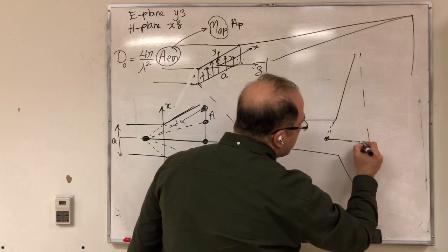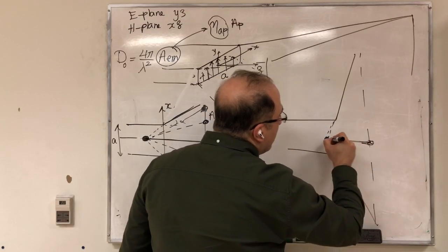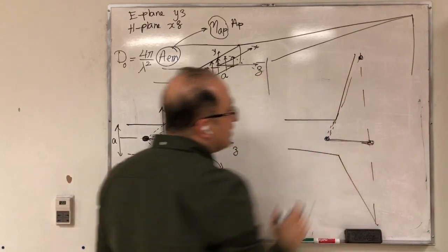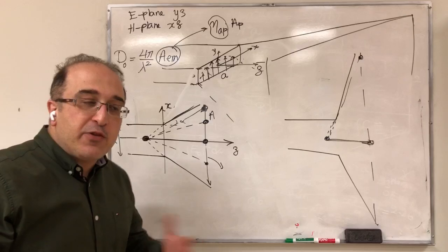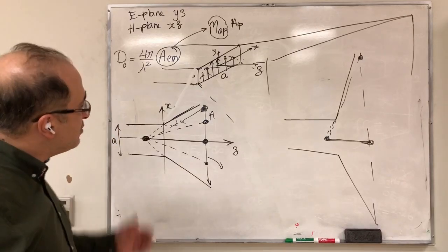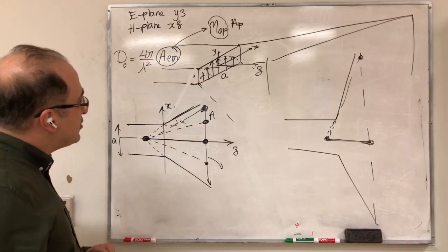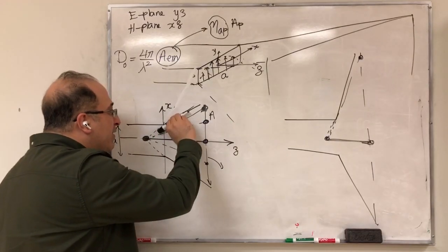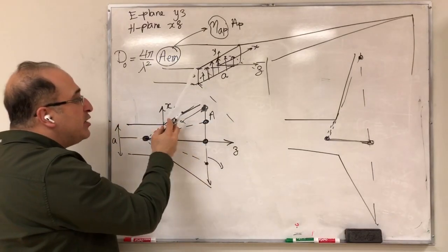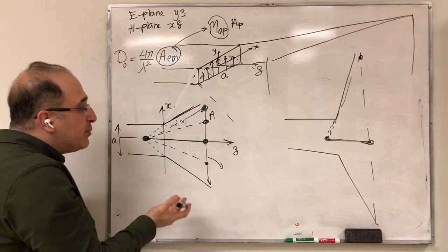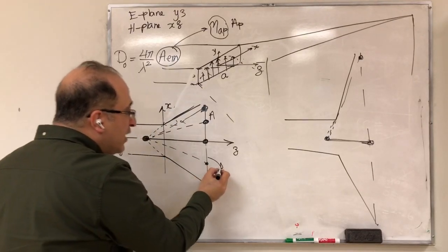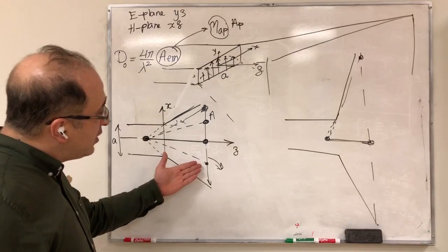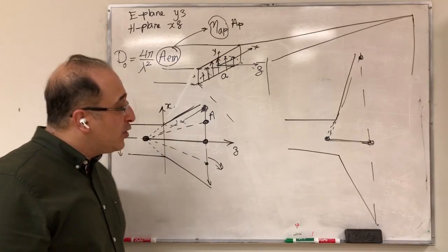This distance is from here to here, and now all of a sudden you have another distance from here which is completely different from this. And these differences, of course, are with respect to wavelengths, but I'm just trying to explain it intuitively here. So the way that you flare out the aperture cannot be too aggressive, because if it becomes too aggressive, you get extremely out-of-phase electric fields here, which are not appropriate for getting good radiation.